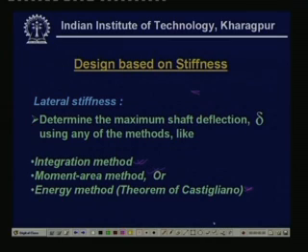However, the main idea is that using any of these three suitable methods, one has to find out the deflection of the shaft. Normally, if there is a series of loads acting onto a shaft, creating lateral deflection, we search for the maximum deflection occurring on the shaft due to the various loads responsible for the lateral displacement.